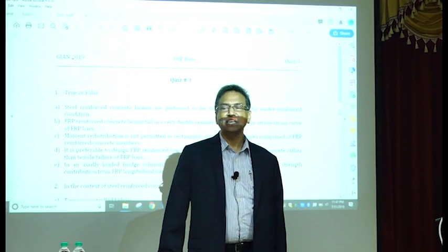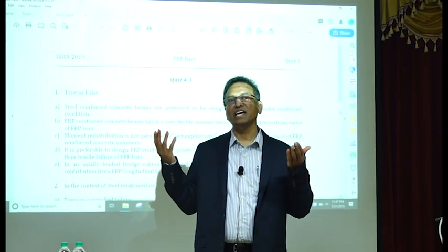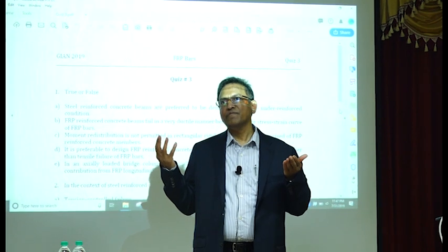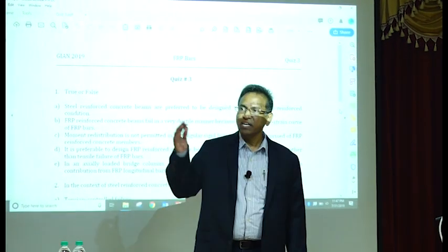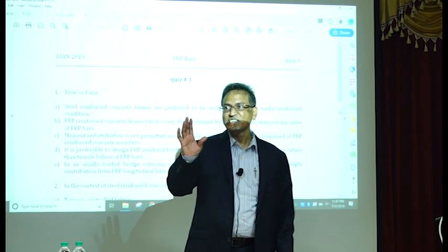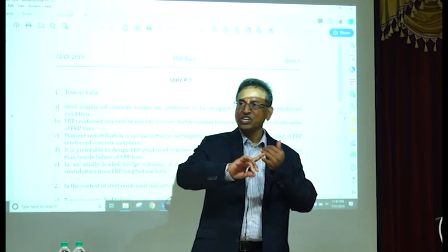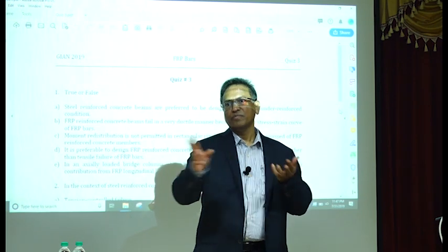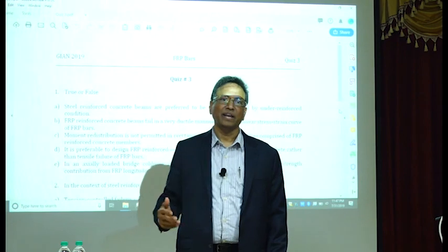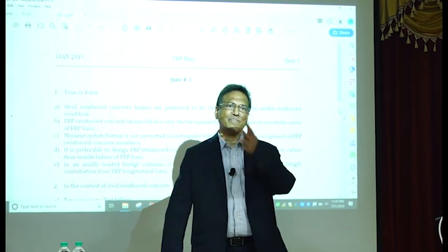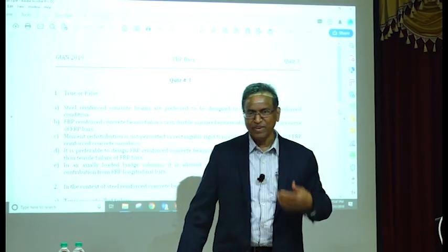Yes. So there is a difference between IS 456, which uses material factors, and ACI, which uses strength reduction factors based on actions. Shear 0.75, for beam 0.65, 0.9. Very good. Anything else you remember you want to say here?